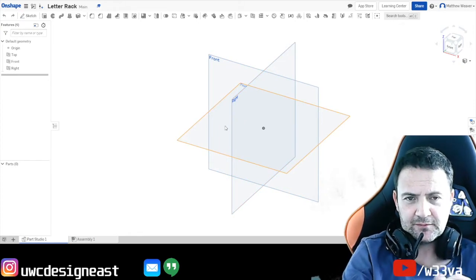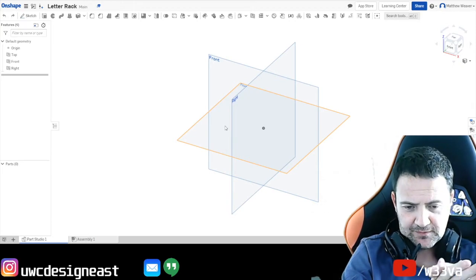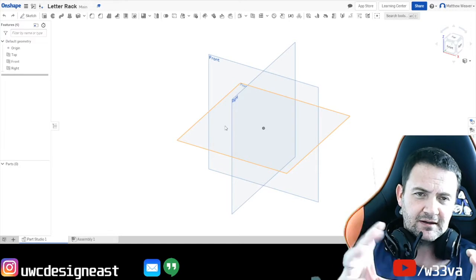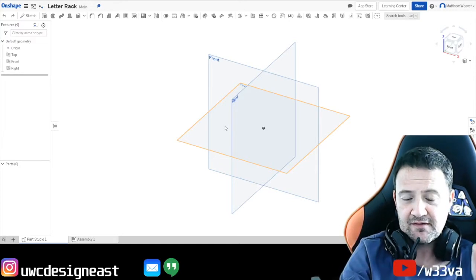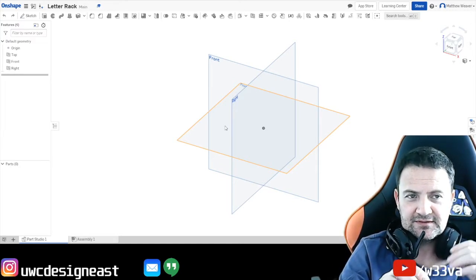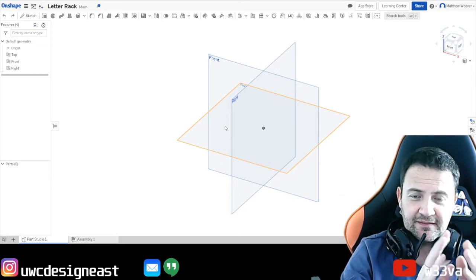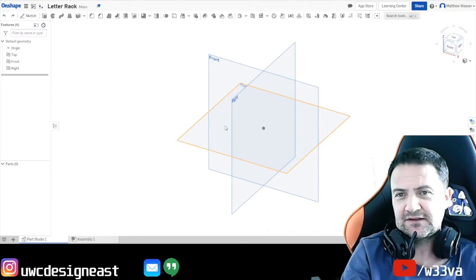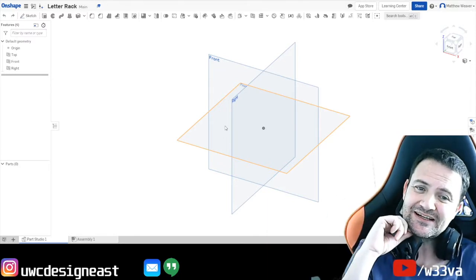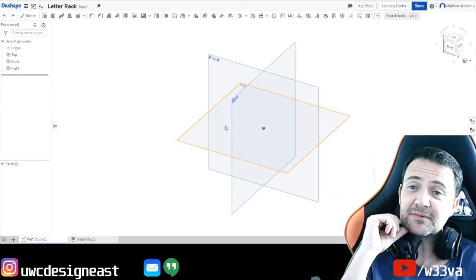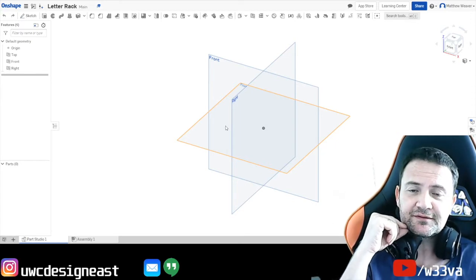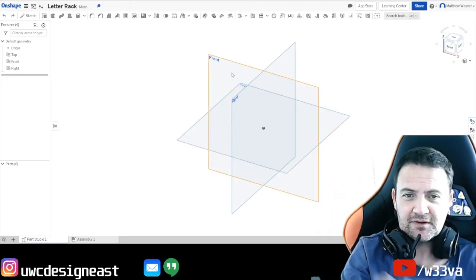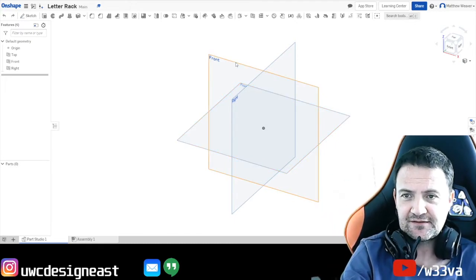Now, if I was to look at the side view, depending on your design, all I would get would be a selection of squares and very, very thin rectangles, because the thickness of the MDF is only 3 millimeters, so you couldn't really see the shape. You would just see the side of the shape. If I was looking at the top, it'd be very similar. I might see the drill holes if you're planning to drill into the main block, but I'm not going to see those shapes. So I suggest that you start your sketch in the front.